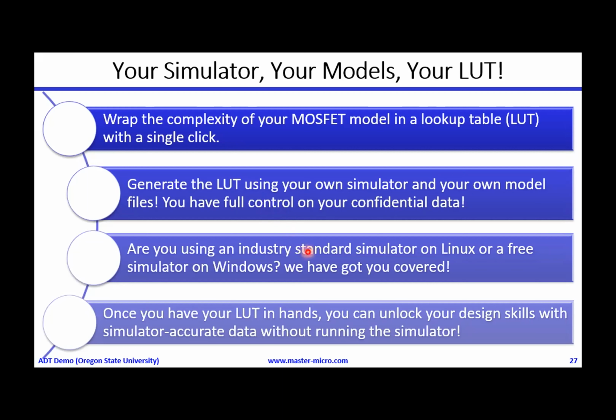So you can use Spectre on Linux, for example, and you can use a free simulator like LTspice on Windows. And once you have this lookup table in your hands, you have all the characteristics of the device, and you can start the design process and do whatever you want, from exploring trade-offs to design tweaking, without running your simulator again. You just need to run your simulator once per technology to get this lookup table, and then you are done. You can do all your design activity in our tool without invoking your simulator again.